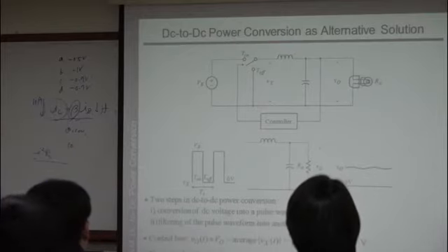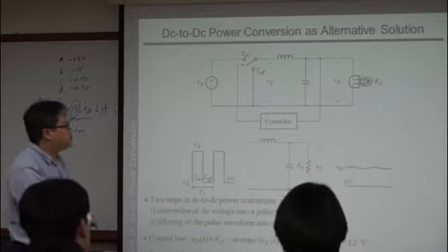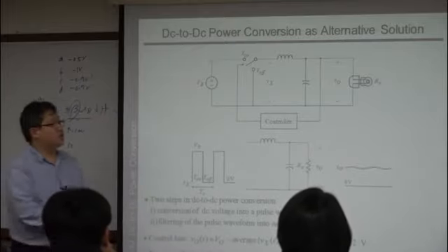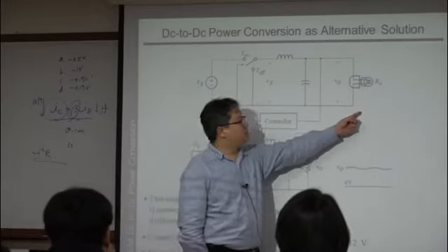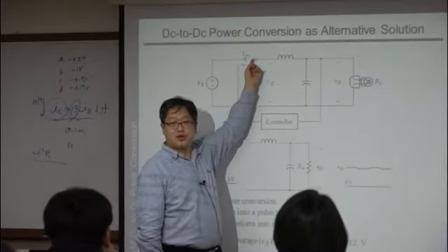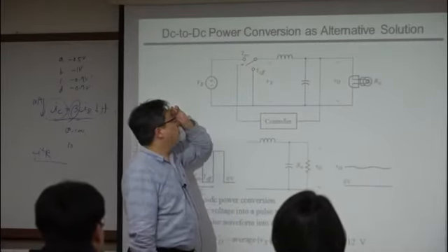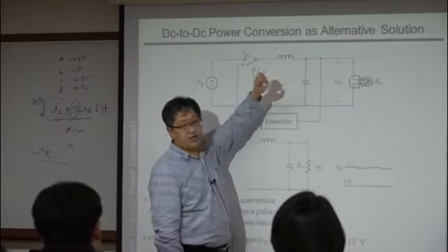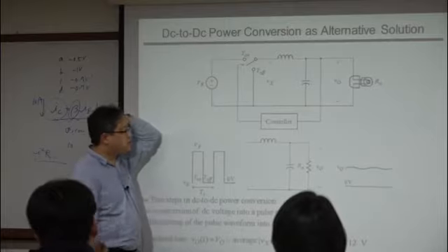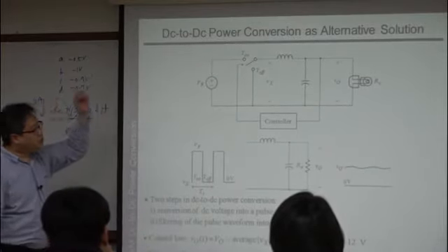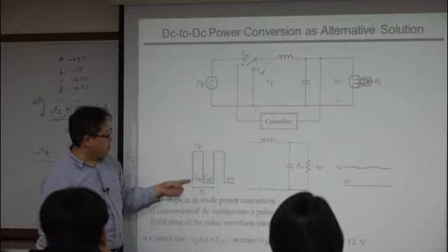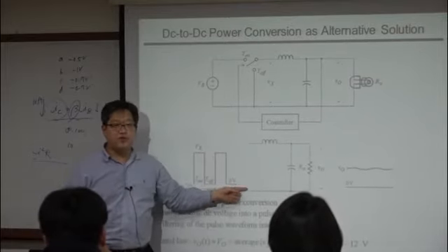Okay, DCDC power conversion as an alternative solution here. Previously, to drive the bulb, you had the resistor, right? But now you have the SPDT switch and LC filter. The role of the SPDT switch is to create this kind of switching waveform.